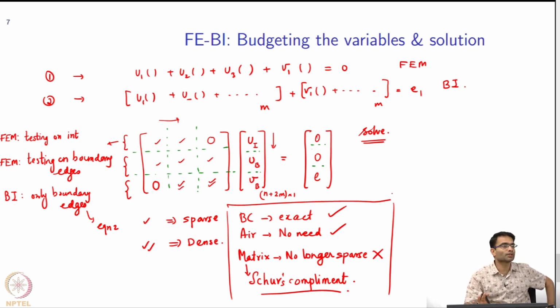Okay. The same principle could also be used if you wanted to write a mode solver to find the eigenmodes of some waveguide using this approach. There also you will have the same problem. You have FEM for a waveguide, but then you need some air outside of it to apply the boundary condition. So why do it? Apply a boundary integral. The idea I want to convey is how to cleverly change the boundary condition and get it from somewhere else. In fact, many of your commercial solvers, like HFSS and so on, nowadays have these options inside, either an absorbing boundary condition or a boundary integral. So now you know what they are doing inside.